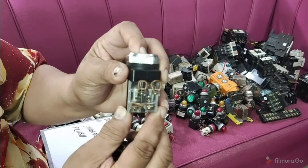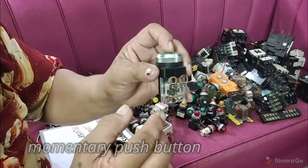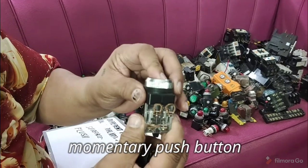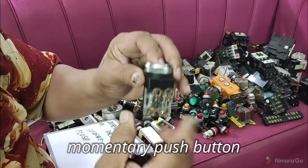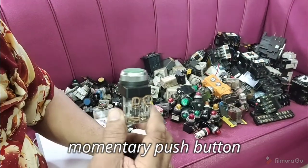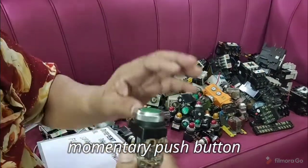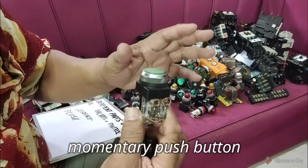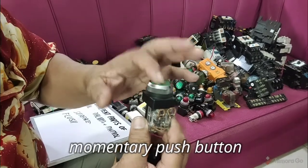So again, this is a momentary push button. You can switch this or push this only for a short period of time. So when you press that one, the motor runs, then release your finger. The motor will already run. Okay? So of course, when I introduce to you the control circuit of the magnetic contactor, or rather magnetic starter, then you can understand the principle of operation here.